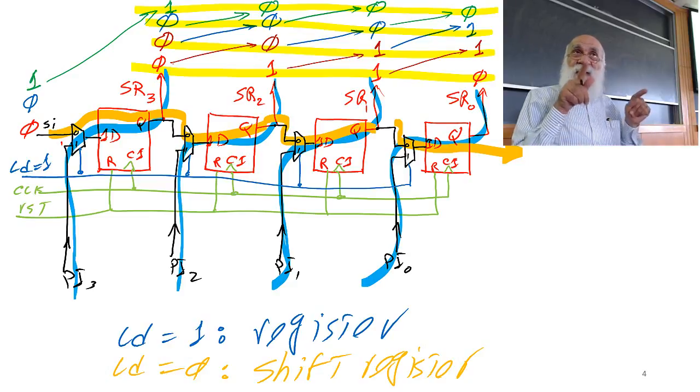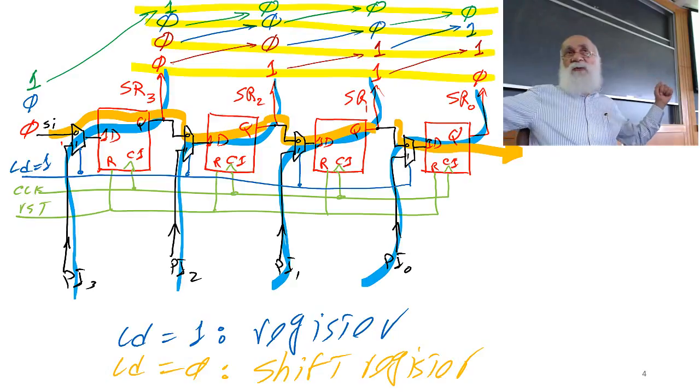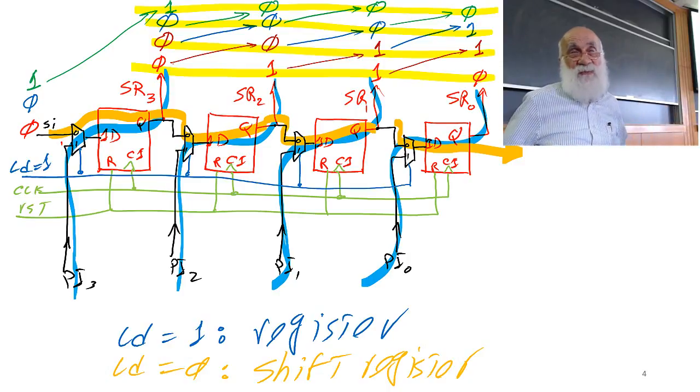It would be transparent. What happens is, as soon as you make the clock 1, the serial input all the way to the left passes through the entire register, makes everything that same value. Okay, so it's not going to work like a shift register. Exactly.